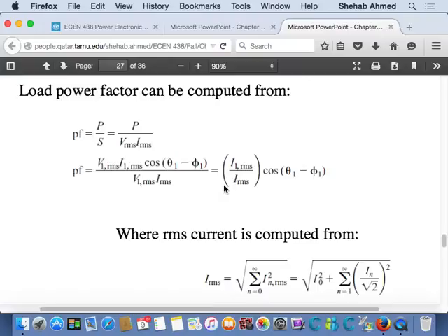At different voltage levels, at 132 kilovolts, they give you a smaller margin for reductions in power factor, and maybe less margin in voltage harmonic distortion.